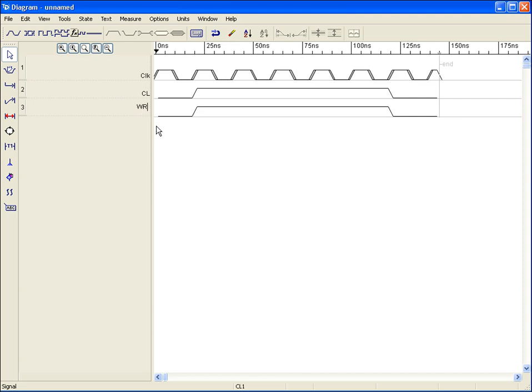We now need to add an intermediate state in the write enable signal. State changes can be added to completed signals using the pulse tool. Once selected, any click in a waveform state will insert a pulse event to the waveform for high, low, or high Z signal states, and a single state change for valid or invalid states.